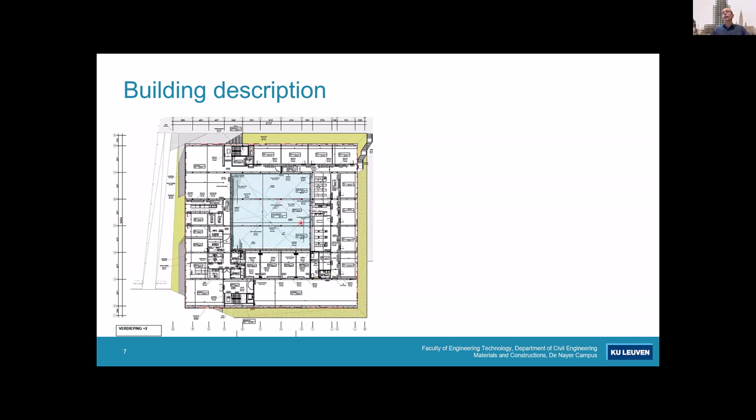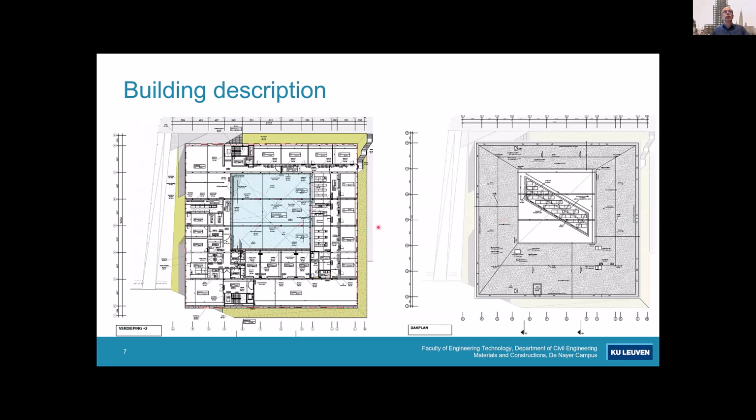And then in the rooftop part, you will see that there are two truss beams. You see already that the truss beams are situated in a regular grid. So there's the first, the second, the third, the fourth, the fifth, the sixth, and then the third and the fourth. Those truss beams are just passing through the whole building, going from inside to outside. On top of that, there is a steel frame, and on that steel frame, there's a cover and some photovoltaic panels. So basically, those two truss beams are connected to each other. There's a stabilizing effect, but I didn't take it into account in the simulations.